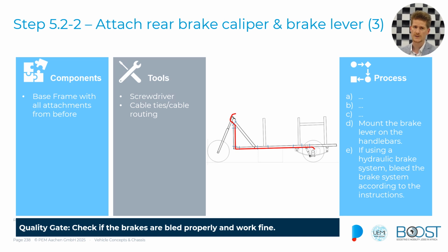So the quality gate would be to check if the brakes are bled properly, and if they work fine. Please make sure that you have trained personnel that really knows what they're doing when dealing with brakes, because they are the most important safety feature on this vehicle, and that they set up the brakes in such a way that they are working totally fine.